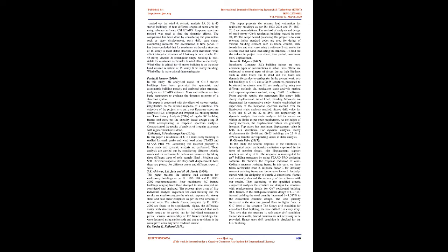Calculate the equivalent horizontal forces. The static analysis method depends on finding the horizontal force caused by the earthquake and applied at the base of the structure level, called the base shear force. Coefficient C is called the seismic coefficient of the region in which the studied structure is established, bearing in mind that the seismic map approved in the Arab world includes 5 seismic regions. Modified Mercalli scale, description of the region, factor Z, region number.